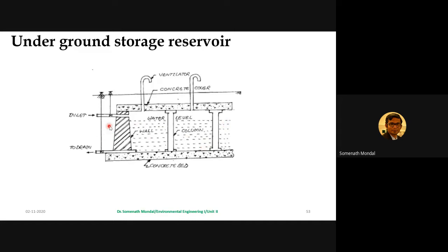However, when the tank is empty, then there is no water within the tank, and in that situation, there will be pressure coming on the side wall, and there will not be any component to counterbalance this particular pressure, and that is why the side wall should be stable enough to handle this kind of pressure difference during the full level of the tank and during the empty situation of the tank. So in both the cases, the pressure distribution in the wall would be absolutely different. Fine.